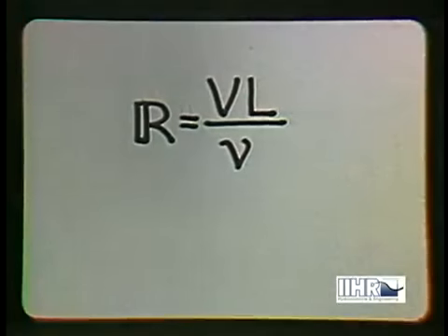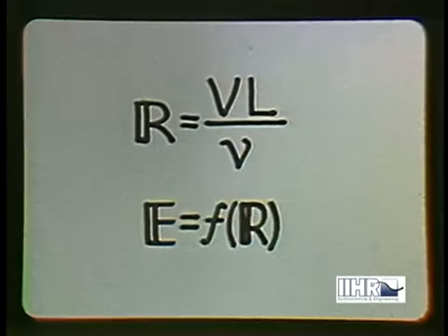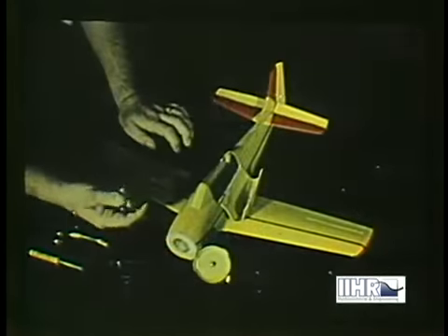One complexity that obviously cannot be modeled is the formation of spray. If, instead of gravity, the viscosity were involved, ratios known as Reynolds numbers would control the Euler numbers, and the velocity should then vary inversely with the length. The Reynolds number becomes the criterion of similarity in the motion of submerged streamlined bodies, like submarines and airplanes.